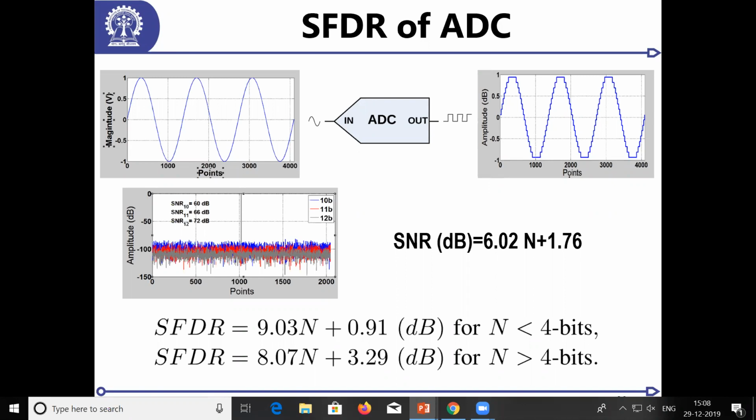Now, in order to get a clean ADC, there should not be any spurs. These harmonic powers are called the spurs. These are spurious signals. We do not want those. So how do we estimate that? In order to estimate that, we use something called dithering, and that is where I want to now introduce something called dither.